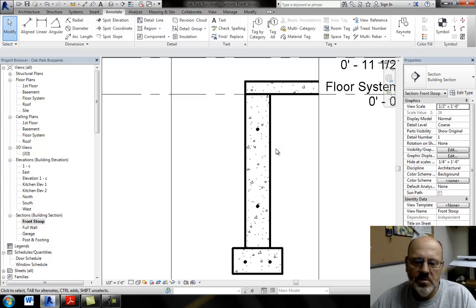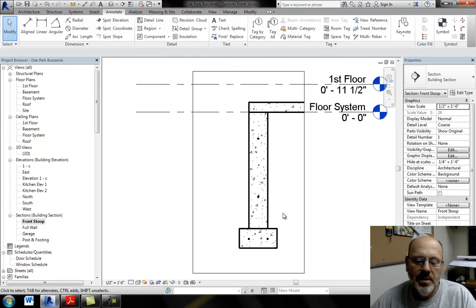That's all we would need on this short wall. On the 8-foot wall, you'll need 1 every 2 foot. So you'll start probably 1 foot up, like this, and go 2 foot, 2 foot, 2 foot.